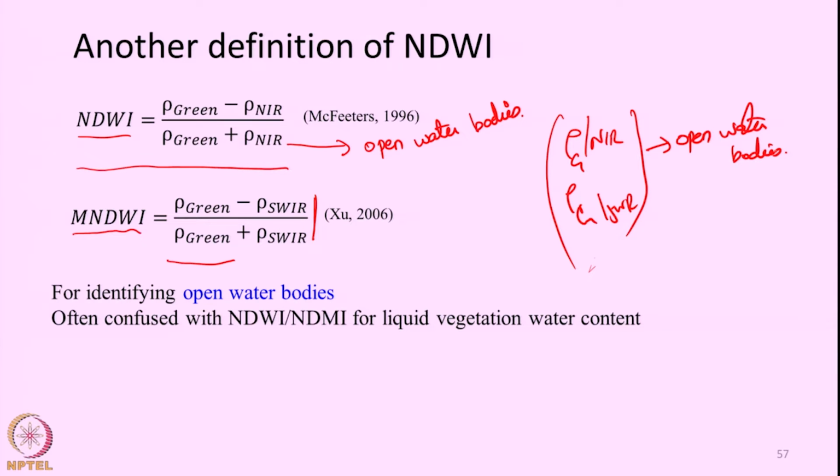Okay, we just saw that NDVI is one of the most widely used indices and is used in various applications related to vegetation and its monitoring. But is NDVI only controlled by vegetation chlorophyll activity, or will something else change the values? There are two important factors we need to consider when we use NDVI for different applications. The first thing is the soil background effect.